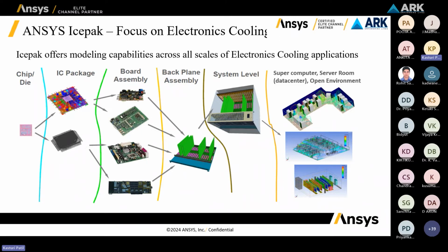So generally when we are going for fabrication, before that we need to do this heat analysis part, and if it is not properly done, then heating problems can be found in many boards. This is where IcePak plays a very important role in thermal management before fabrication. So all detailed analysis we can do in IcePak.